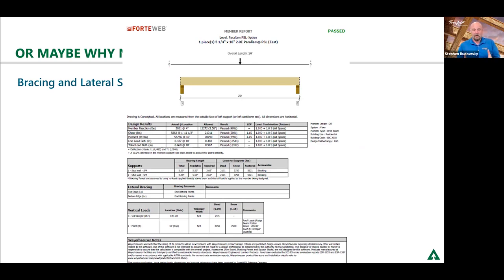So unless you're working on something that's uniformly loaded from the top, this is always going to have to be looked at to make sure that if nails aren't going to be the solution, are we going to need some type of structural screw to transfer the weight from the inside ply, where you may be hanging material, to make sure that it's transferring all of that load and stress to the second, third, or fourth ply out. We're actually going to look at that a little bit later in the discussion.